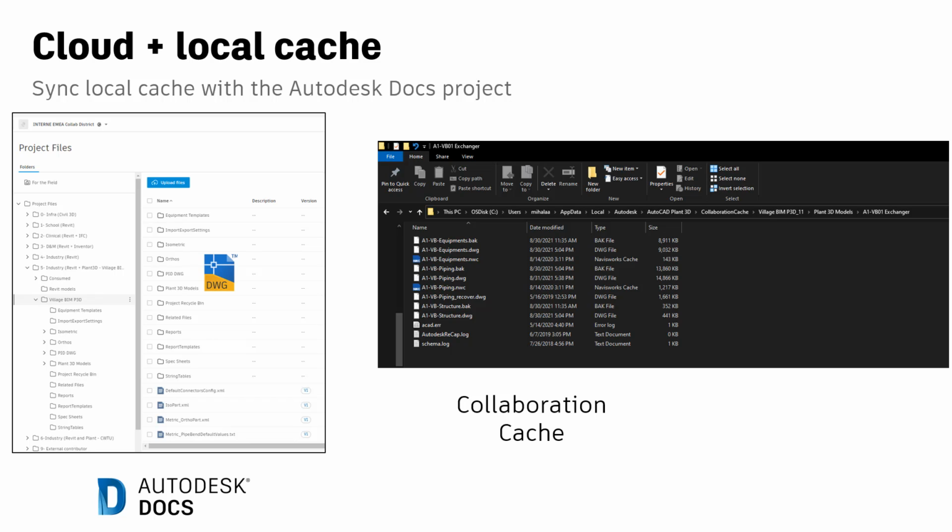For example, for an AutoCAD drawing, the Plant 3D drawing or Civil 3D drawing, in this case, we can see it on the cloud. And then when somebody needs to work with it, he or she performs an operation of checkout, which results in locking the file on the cloud in the master project. This person can actually modify the file, so co-author it, add new elements,